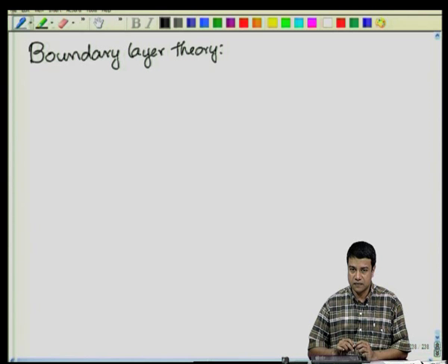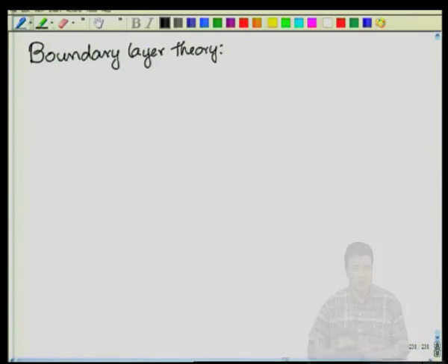Then we looked at the high Reynolds number regime, and in this case you can actually get non-trivial solutions for the velocity field, because the momentum equation contains the pressure. In the concentration and the temperature equation in mass and heat transfer, the solution just reduces to a first order equation, partial C by partial t plus u dot grad C is equal to 0. Whereas in the case of fluids, we also have a pressure which is required to enforce the incompressibility condition.